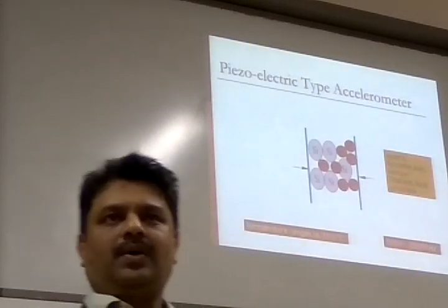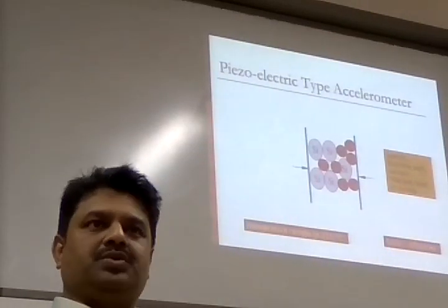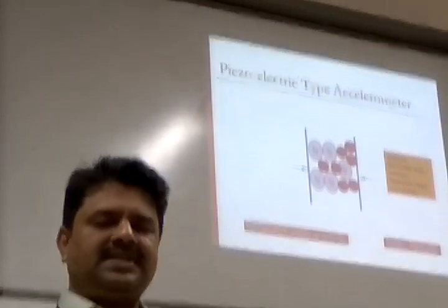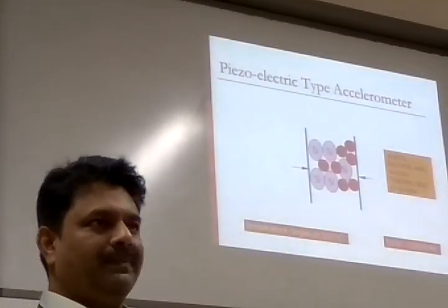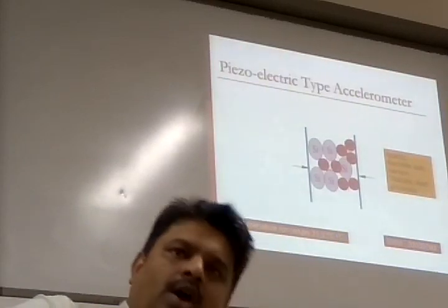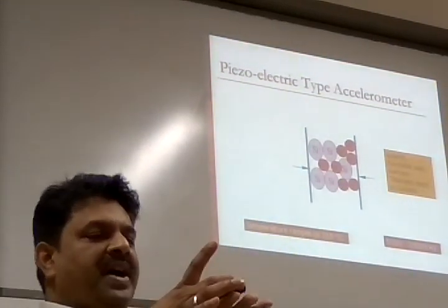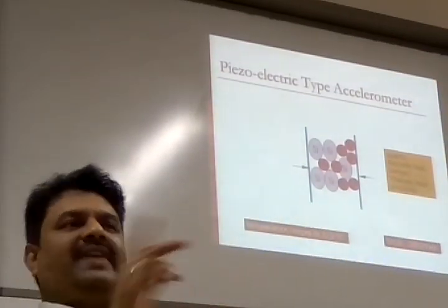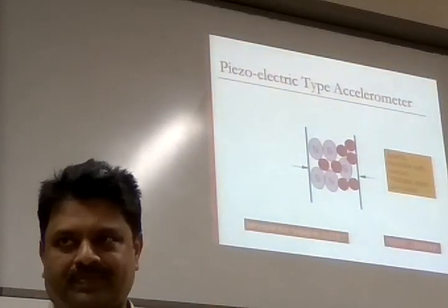Piezoelectric type is what you have to learn in detail, but there is nothing big to learn. Widely used. Okay. What is widely used? Piezoelectric principle: piezo means force, electric means you know electric. When a force is applied onto two parallel sides of a crystal, on the other two parallel sides electric charges are developed, and vice versa. This principle is called the piezoelectric effect.